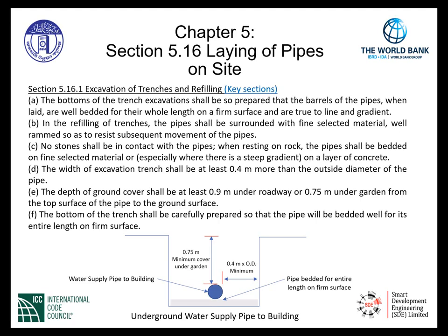B, in the refilling of trenches, the pipes shall be surrounded with fine selected material, well rammed so as to resist subsequent movement of the pipes. This section mandates that the materials become rammed and compacted around the pipe to actually secure the pipe in place to prevent movement of the piping system.